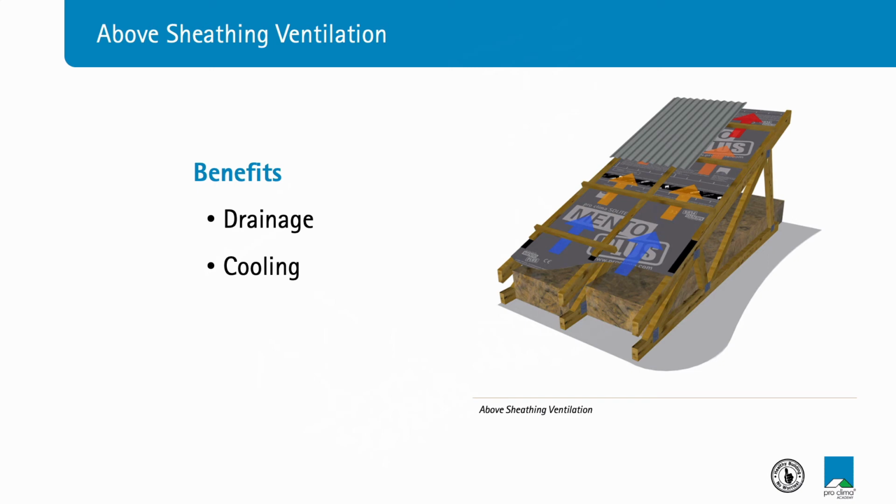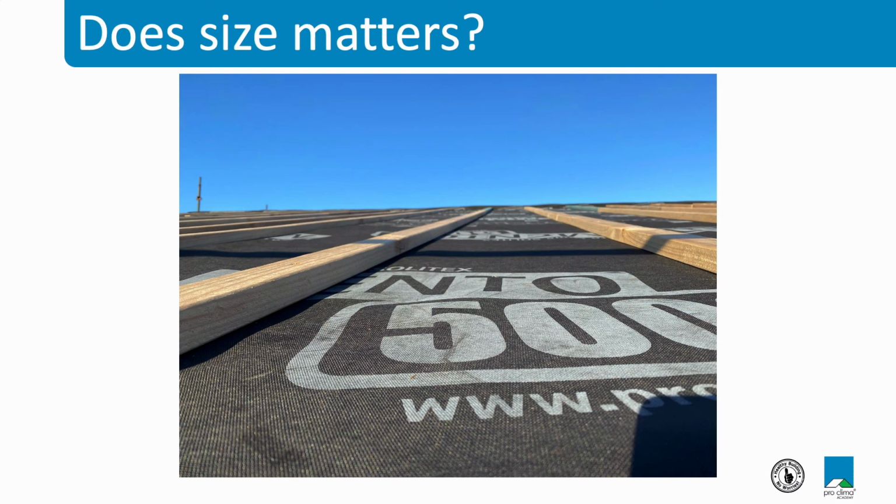The air exchange cools the whole structure, so we're not exposing the rest of the house to those extreme heat conditions or to the extreme cold conditions either. And the movement of air contributes to significant drying of the whole assembly. So the main question is, does size matter?